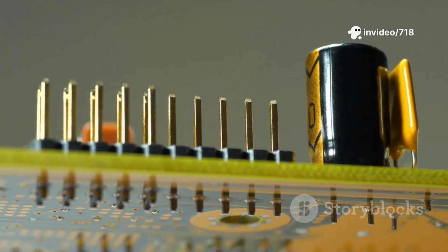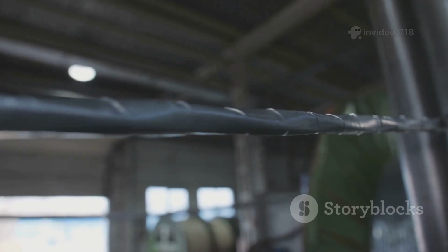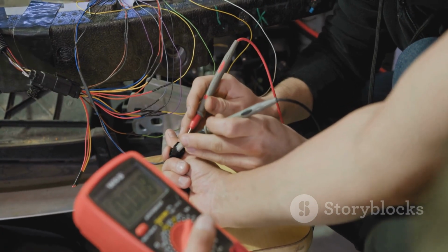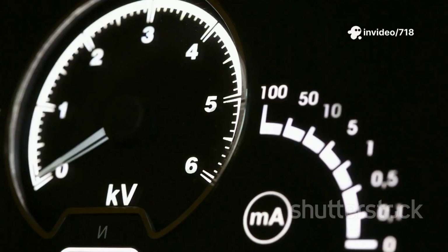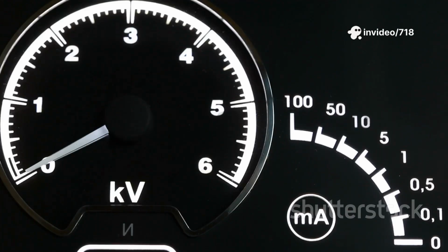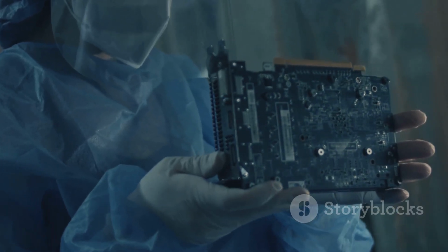The bit line itself has a much larger capacitance than the tiny storage capacitor. So, when the charge from a one cell flows out, it only causes a very slight increase in the bit line's voltage. Similarly, a zero cell causes a slight decrease. The difference is minuscule, perhaps just a few millivolts. Detecting this faint signal is one of the biggest challenges in DRAM design.